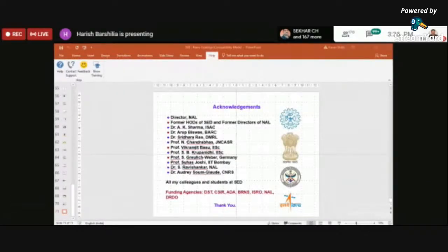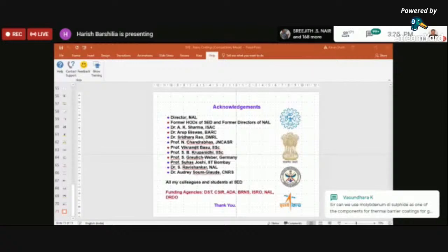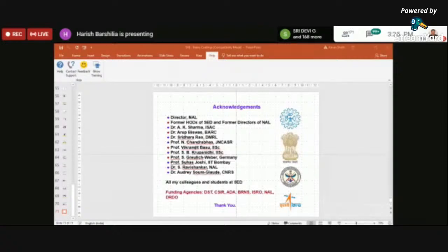So to achieve that kind of performance, you can use molybdenum disulfide or tungsten disulfide. Now the problem with these so-called dichalcogenides is that they work very well in the space environment, that means this inert environment, but they will not work when there is moisture.